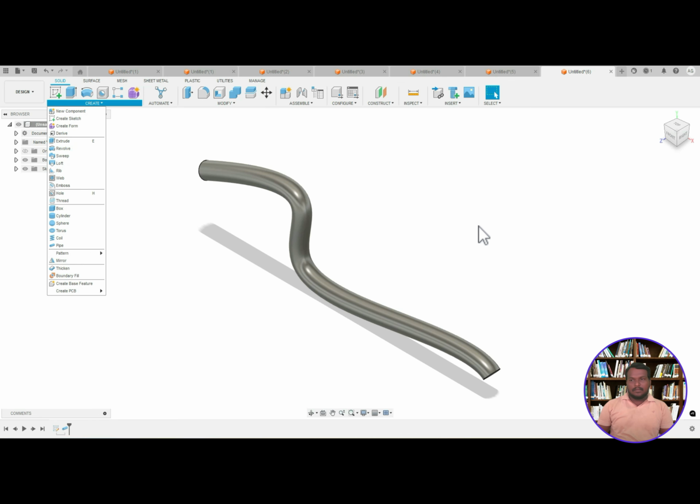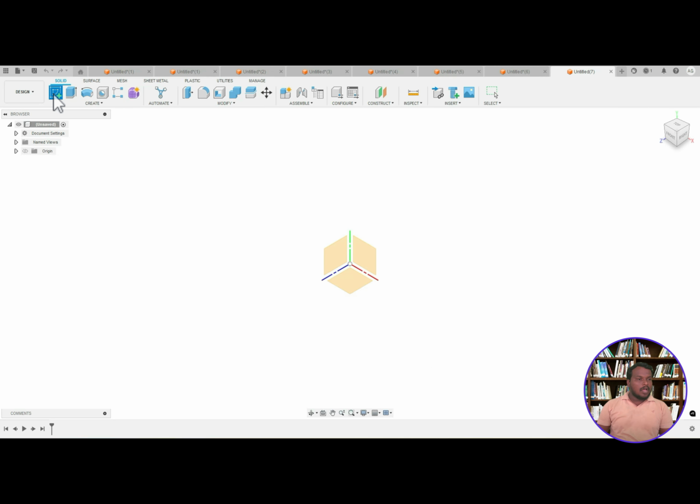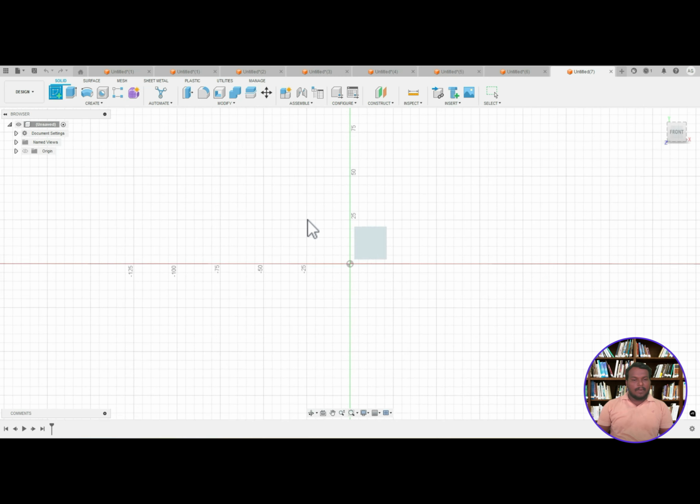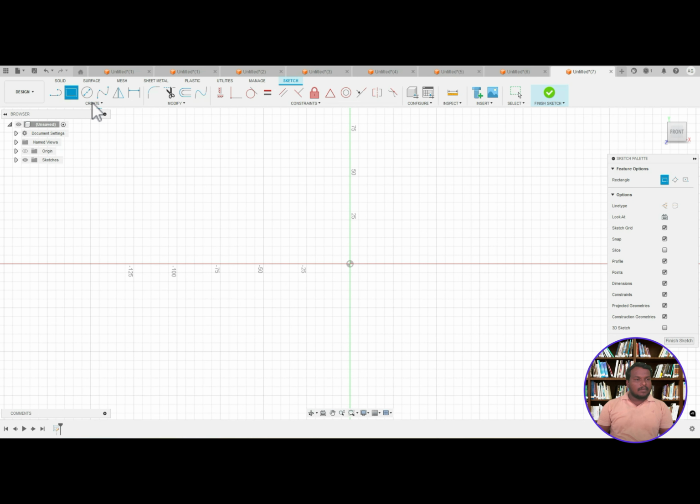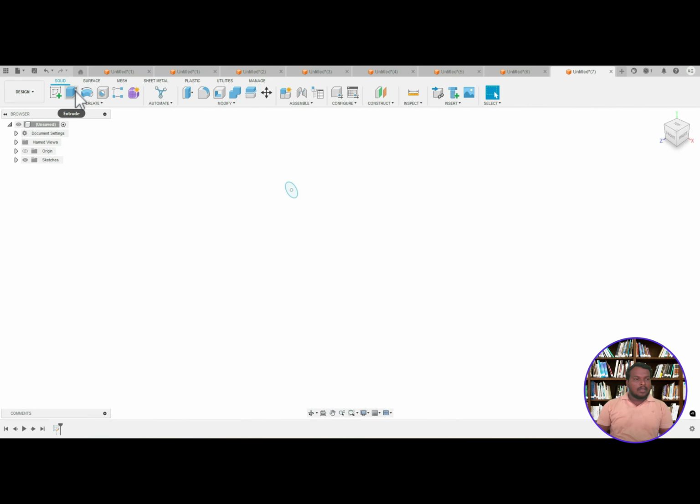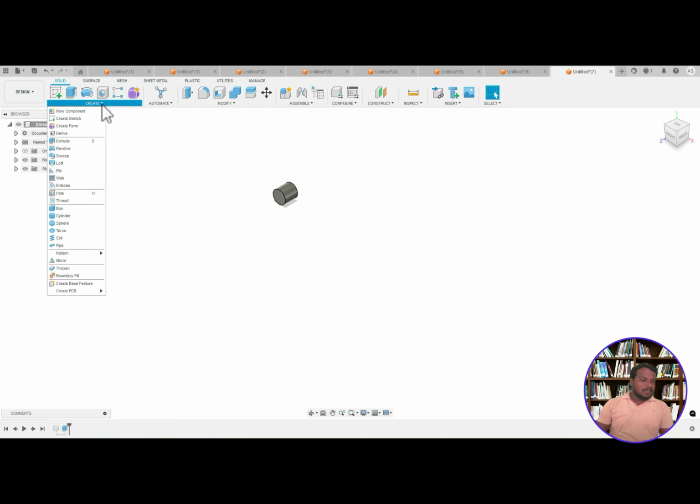Okay. So we'll do some. Okay. So go to new sketch. I'm drawing, for example, on the right plane, one circle with a diameter of 10. Okay. Next extrude 10 mm. Okay, it's done. So we'll go to the pattern.